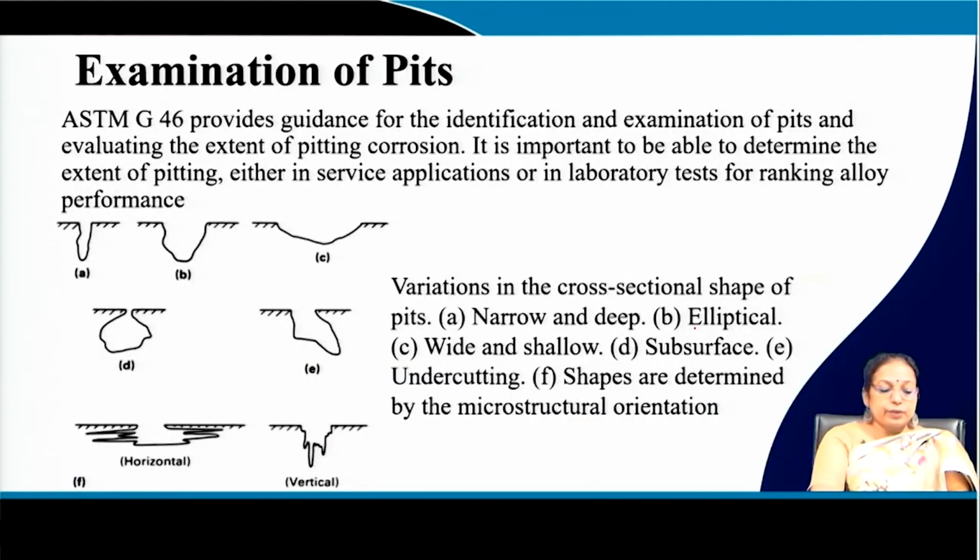So, you can examine the pitting corrosion. As I said, on the surface you measure the area fraction of pit. If you see the cross section, you will see that the pits are not growing in the same fashion; somewhere it is in a capillary like fashion, somewhere it is triangular, somewhere it is zigzag. So, in different fashion pitting grows. If you are interested to know exactly the pitting corrosion behavior or exactly the material loss due to pitting, you have to measure the overall volume of pitting.